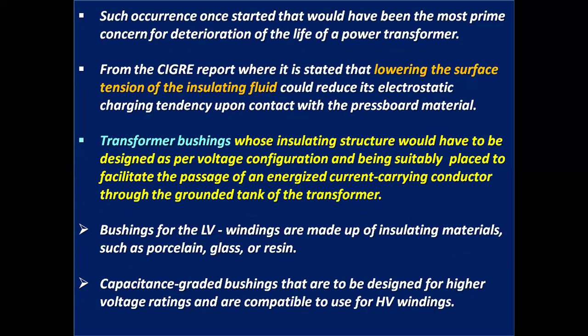Such occurrence, once started, is the most prime concern for deterioration of the life of a power transformer. From the CIGRE report, it is stated that lowering the surface tension of the insulating fluid could reduce its electrostatic charging tendency upon contact with the pressboard material.